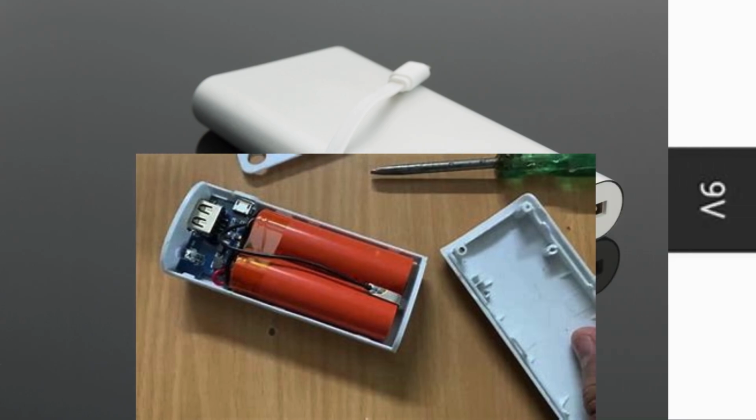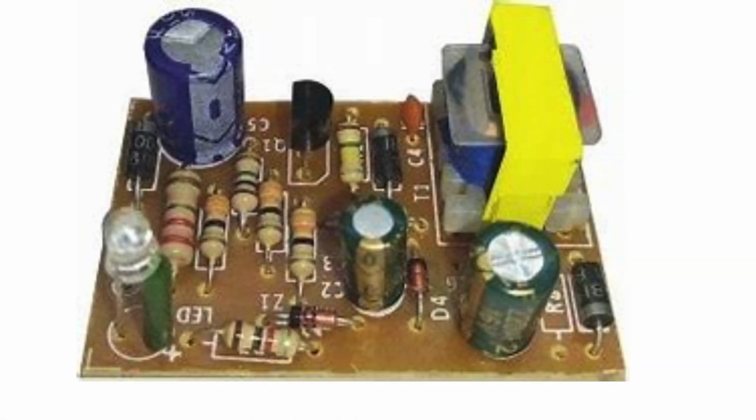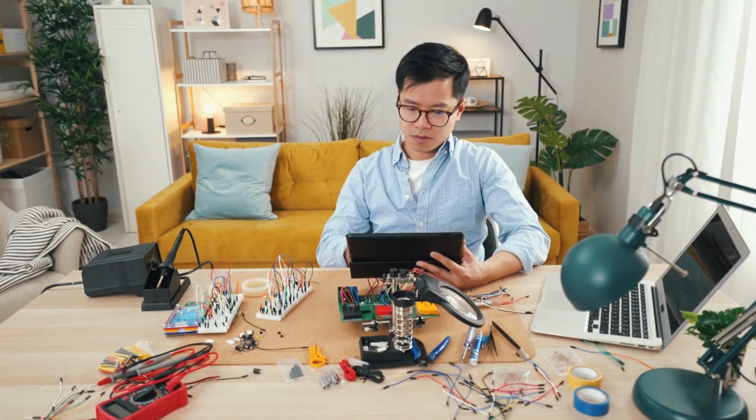You want a simple example? Just grab a modern LED bulb. Even though it seems basic, it contains a driver circuit that converts AC to DC. It regulates voltage and controls the current flow using resistors, capacitors, bridge rectifiers, and sometimes even tiny ICs. It's not just a bulb, it's a mini power conversion system packed into a small shell.